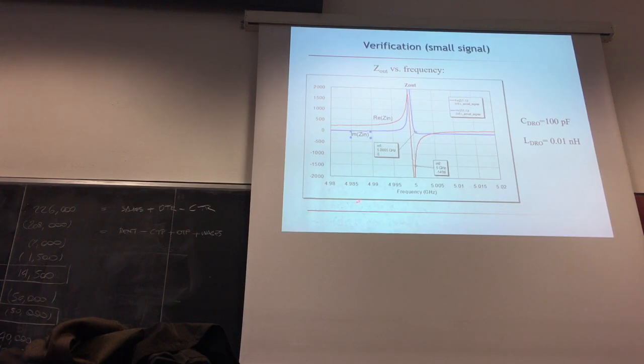Actually, we impose 5 gigahertz, okay. But at the end of our transient, we are not sure that the oscillating frequency will be exactly 5 gigahertz. However, it will be inside this range. And since this range is extremely small, the frequency will be very, very close to 5 gigahertz. And moreover, it will be constrained to stay inside this range. So this is the reason why this solution is very stable, because we are constraining the oscillation to stay inside this very small range.